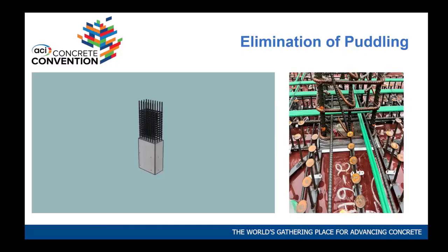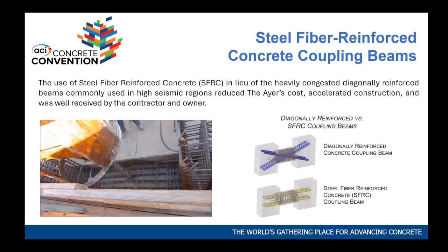It's like a midpoint bar that goes into that joint. And then they put stay foam again up here after they put the top bars, and they pour it. Much easier than putting two mixes, trying to intermix them, and so on and so forth. So that was a big thing on constructability and buildability.